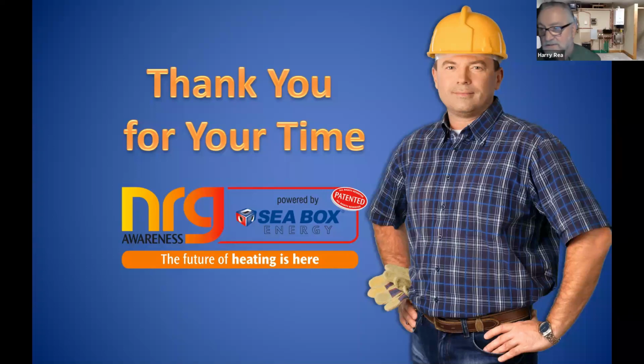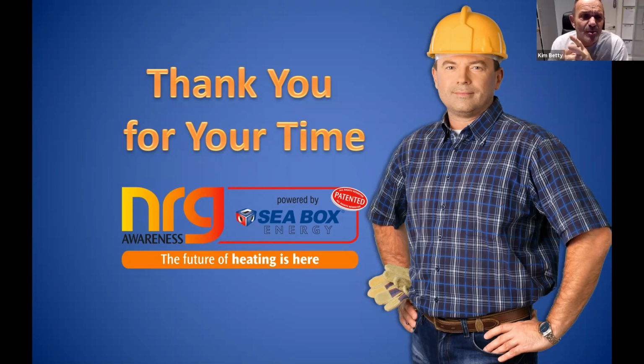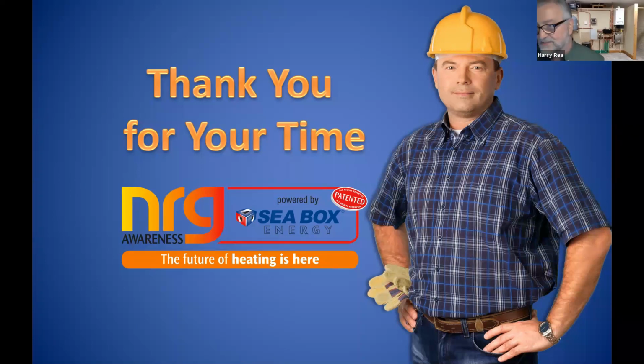It sounds quite an amazing and very flexible piece of kit. What's the target velocity inside the box itself? I was just looking at the air separation and how you go for turbulent flow. So what's the target velocity? I mean, the target velocity of your system, somewhere around 1 meter a second. The minimum is 0.6 of a meter.